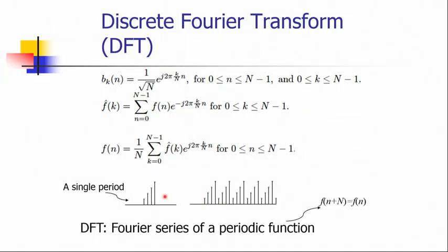So, it becomes a periodic signal, and as you know, any periodic signal can be expressed as a linear combination of sinusoid functions, and you can perform a Fourier series. That is what you are doing here, and while performing the inverse Fourier transform, you are only performing it at these 4 sample points.